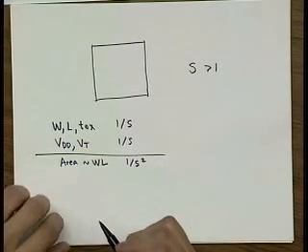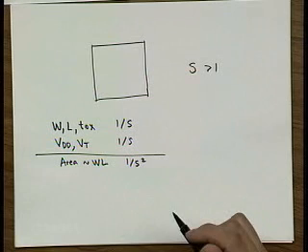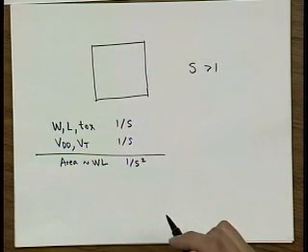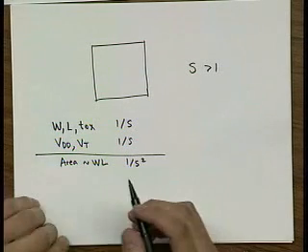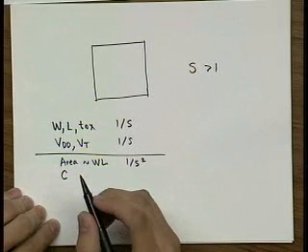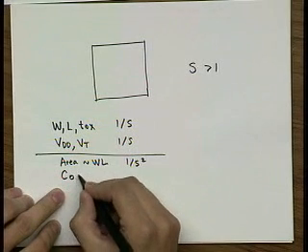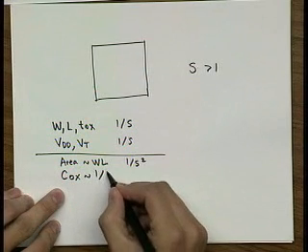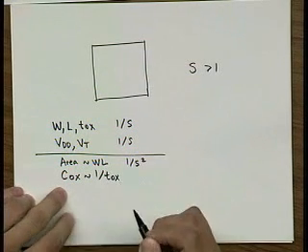Now I would like to know about the speed. The speed is defined by two parameters: your capacitance and equivalent resistance. That's the propagation delay. My capacitance depends on the gate capacitance, or oxide capacitance. I know that oxide capacitance is inversely related to T_ox.